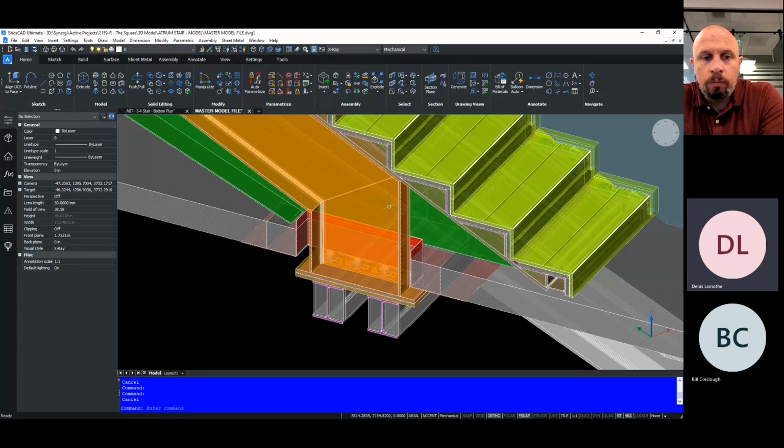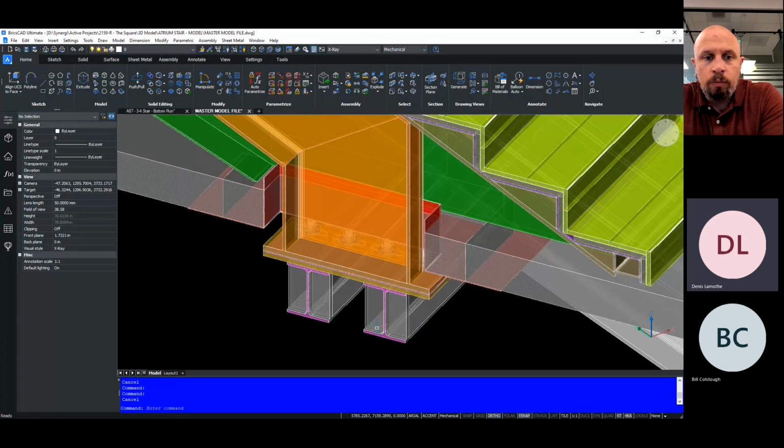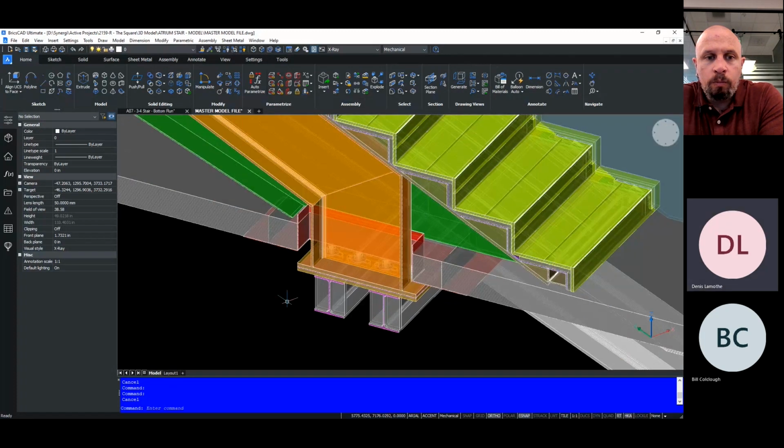And that kind of work is often done before we even have a chance to actually do the submittal drawings of the stairs. So it might be a situation where we have the cart in front of the horse. You know, we haven't finalized the design of the stair, but we've already kind of anticipated where we want the embed plates and hope that we can design our stringers to meet with that embed plate.